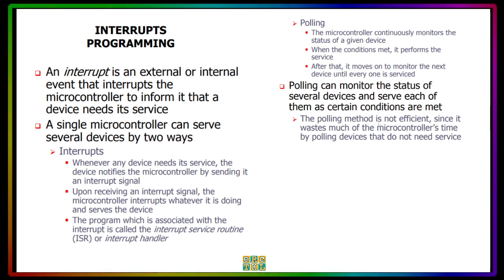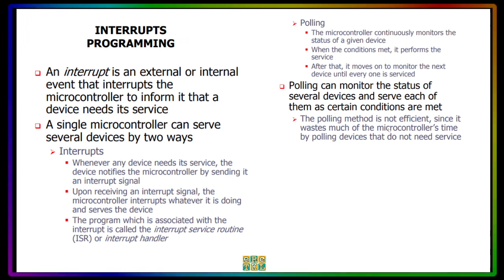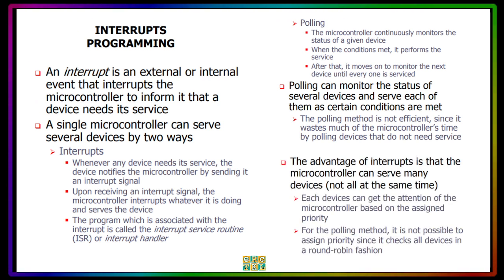The polling method is not efficient because it will waste much of the microcontroller's time by checking or monitoring or polling the devices that don't really need its service. Now, the advantage of interrupts is that the microcontroller can serve many devices, but not all at the same time. But the good thing here is that each device can get the attention of the microcontroller based on the assigned